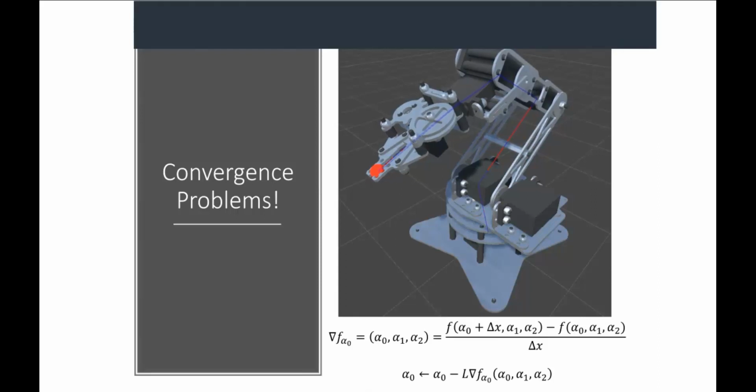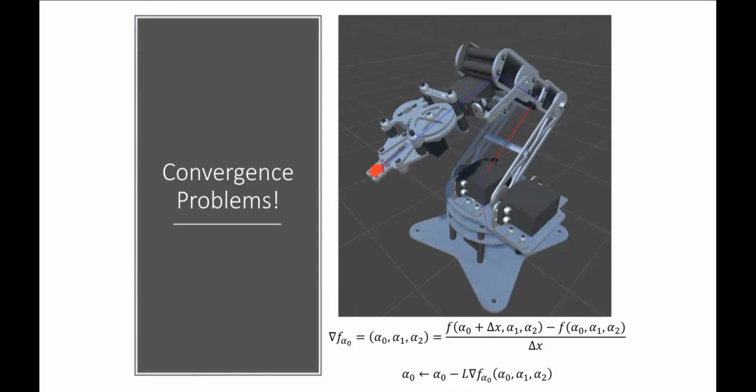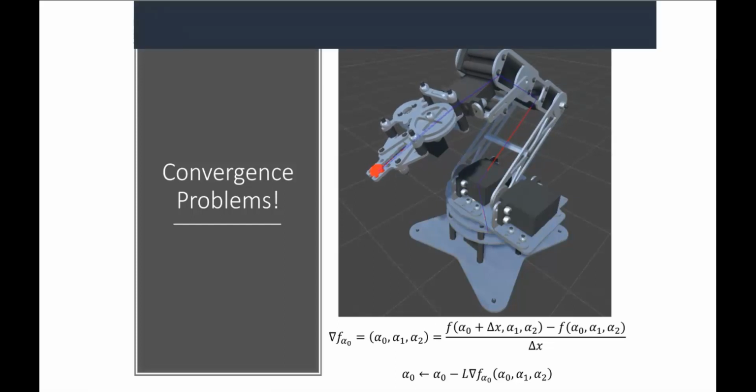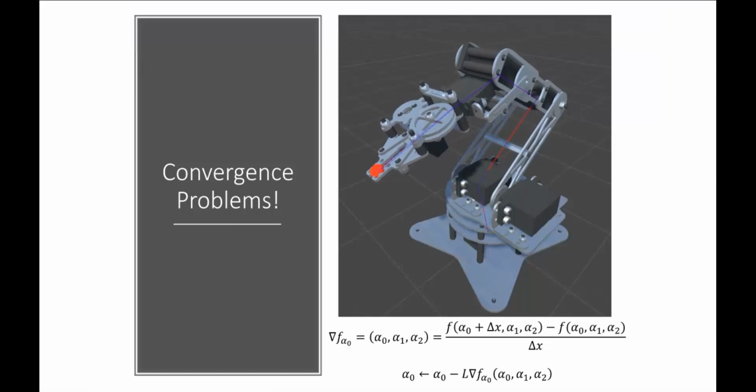So we talked about the step size, the learning rate here. What other parameter could be causing some kind of problem with this estimate? Maybe if you can't calculate the inverse of your Jacobian. Okay, yeah, so there are definitely numeric issues that can come up. Like maybe I've asked for a position that the robot can't even get to, right? And so there is no convex guarantee that's able to hold for the actual achievable space.